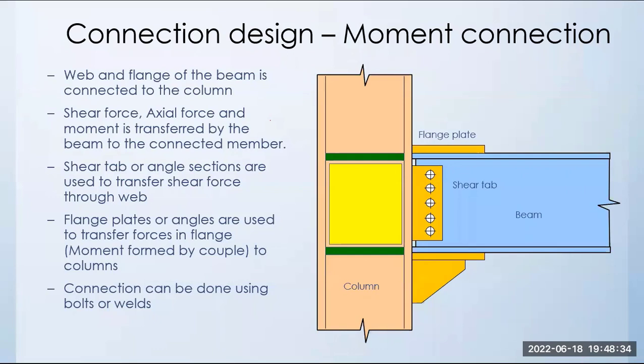Yes, any grade of steel can be used, but you need to cross-verify the seismic requirement, because a higher grade is not recommended in a highly seismic region. That is because ductility will be lesser in high grade steel. So just refer to that.